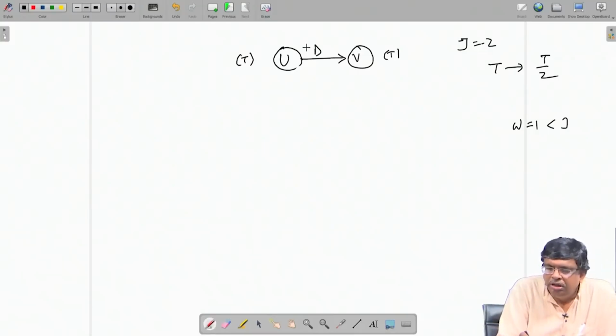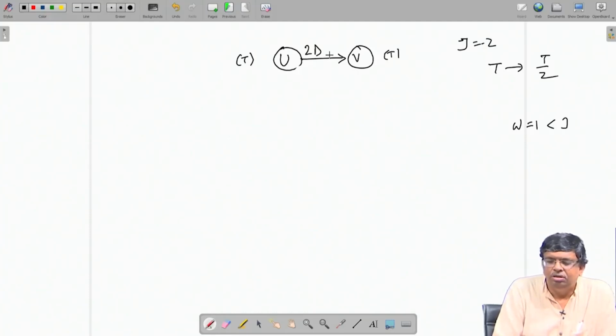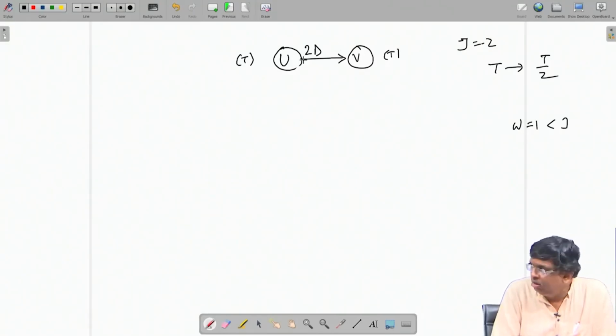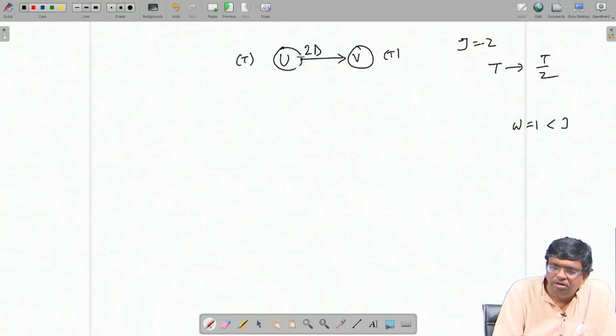If instead of 1d, I give 2d, even then the critical path here is t. So the input clock cannot be shorter than t, the clock period, because whether it is d or 2d or 3d, that does not change anything. This is working in one cycle, taking t amount of time, and it is given in another cycle here, taking t amount of time. Okay, we have done this. So the critical path remains t, but now after making 2d here,